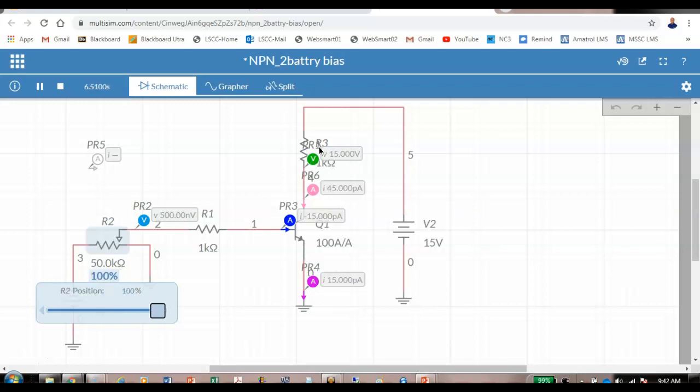So now the transistor is dropping all the voltage. And when I swing it over on this side right here, the transistor is almost dropping 0 volts. So 45 millivolts across the transistor. So there's basically 15 volts across the resistor. You'll see that?